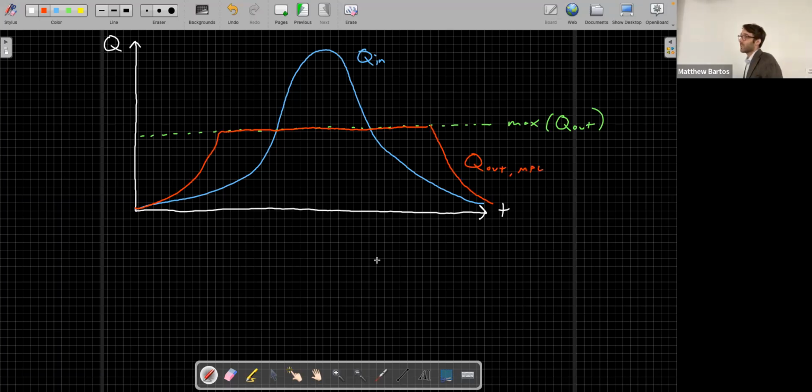If we use feedback control like LQR or full state feedback control, the system will overflow, because the control won't start until you've already deviated from your reference, and you won't have enough actuator authority to get back to the reference once the peak of the flood wave gets really high. So you need to plan out your control actions ahead of time.